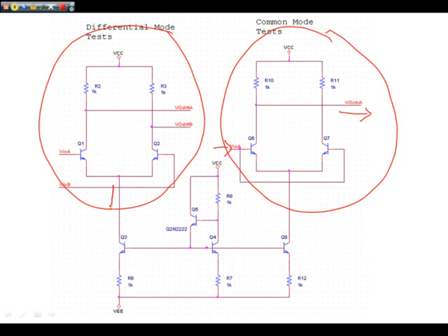So in our differential design, the piece of work that we're really going to do now is we're going to design this current source, and we're going to call it I-tail. This one here is an exact copy. That's I-tail again. Our design parameters start off with VCC. You'll build your Kirchhoff's voltage loop around this system. This effectively will be our reference resistance. This transistor is feeding base currents into all three devices, and this one is our reference VBE value. Down the bottom we have emitter degeneration.